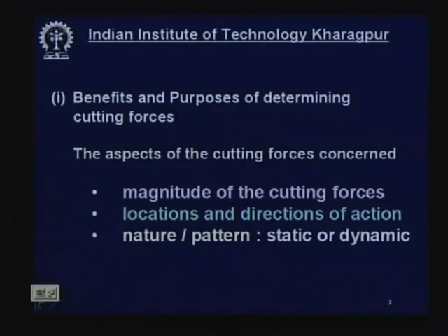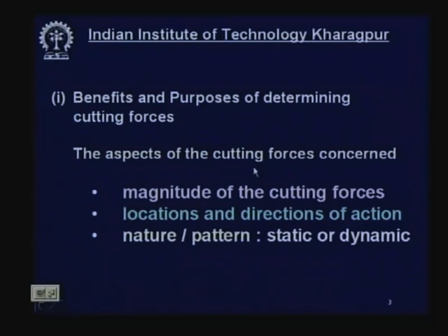Now, first let us see the benefits and purposes of determining cutting forces. Why should one learn this subject? Why should we try to determine either theoretically or experimentally the cutting forces? Before we do that, we should know what major aspects we are interested in about the cutting force. As far as the cutting force is concerned, the magnitude of the cutting force is most important. Then the locations and directions of action of those cutting forces in the machine, and the nature or pattern of the cutting force, whether static or dynamic. If dynamic, then what is the frequency and amplitude.